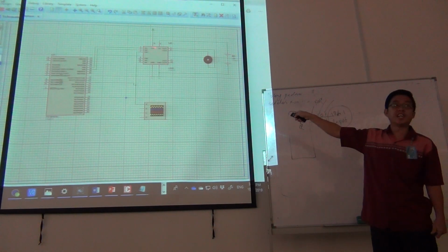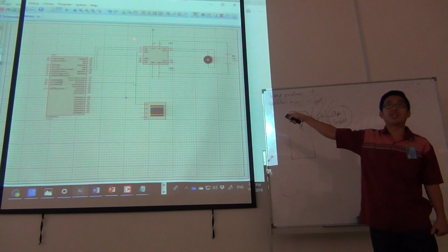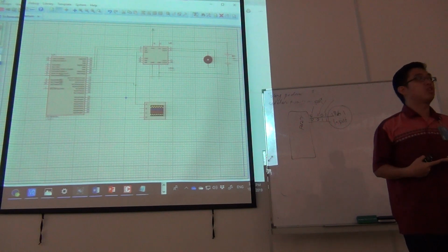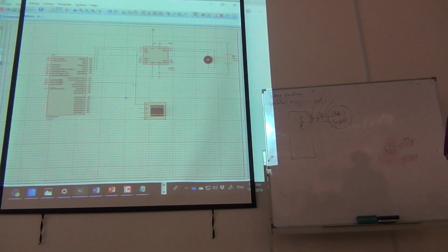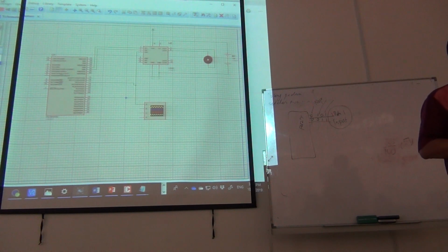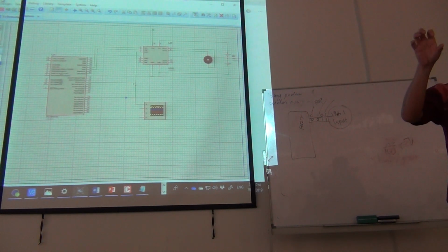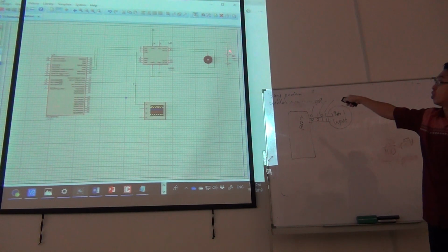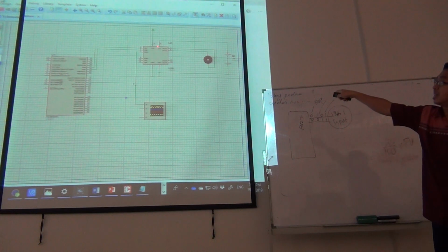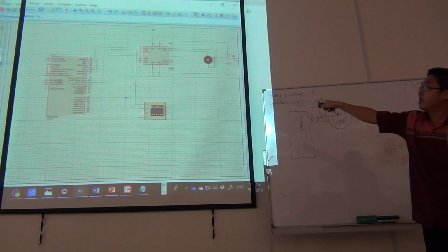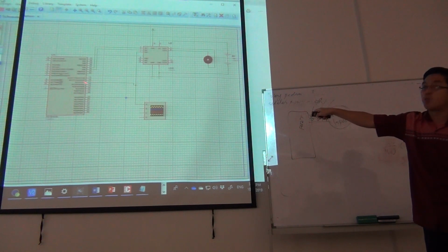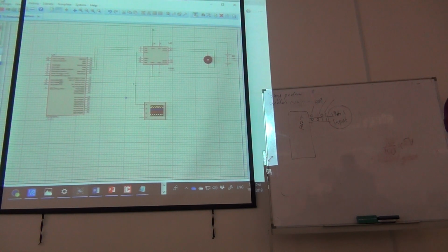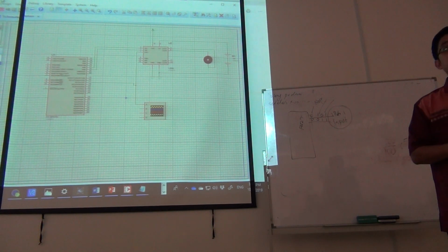And for VS over here, I'm using an external 12 volt battery, which means that my motor is using a 12 volt battery to operate. Without that 12 volts, your board cannot function, because your board can only give you 5 volts. So in the example here, my motor is operated by 12 volts, connected to VS. Your enable pin is connected to CCP1. I'm putting CCP1 here because on the board it is the same node. CCP1 and CCP2 are sharing together because it's on one board only.